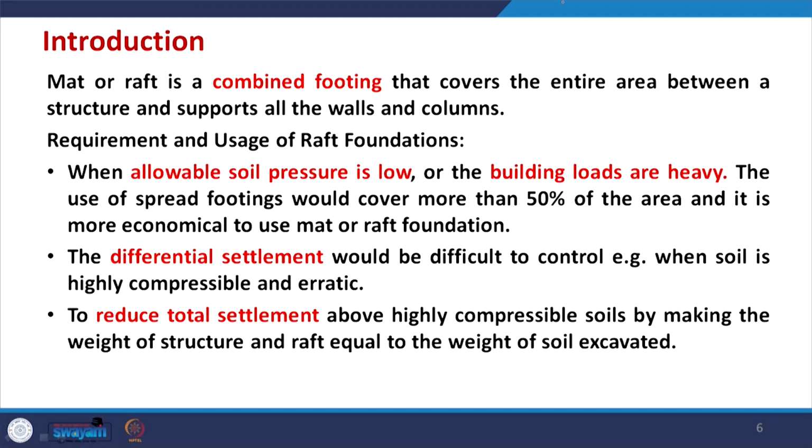Further, the raft or mat foundation will help in reducing total settlements, particularly above highly compressible soils, by making the weight of the structure and raft equal to the weight of the soil excavated. Many times we call this a floating foundation. In that case, you excavate the soil, and after excavation you put your footing and the structure. If the weight of the excavation is the same as the weight of the superstructure and footing, there is no change in the stress at that point, and even if your soil is very weak, it will still be able to carry all the loads of the superstructure.